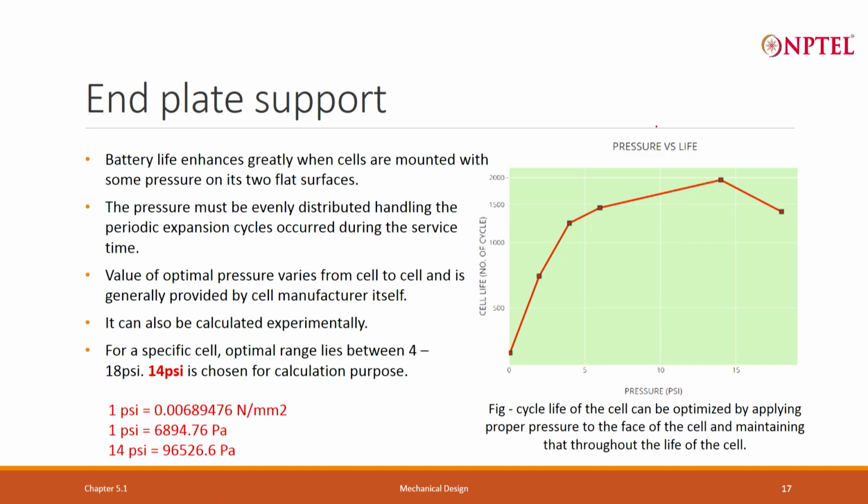So, this is how we have calculated everything for the base plate, the maximum bending stress and the maximum deflection. These were 2 parameters for us, which we have solved. We got a particular thickness, and if we did not like that thickness, that is, if this thickness is too much for my pack, we also found how we can reduce the thickness further by providing ribs and stiffeners.